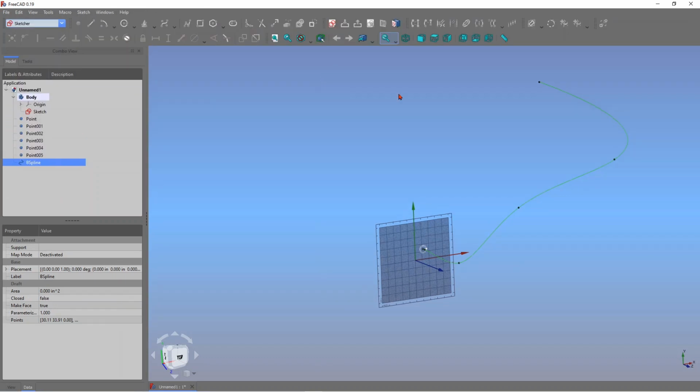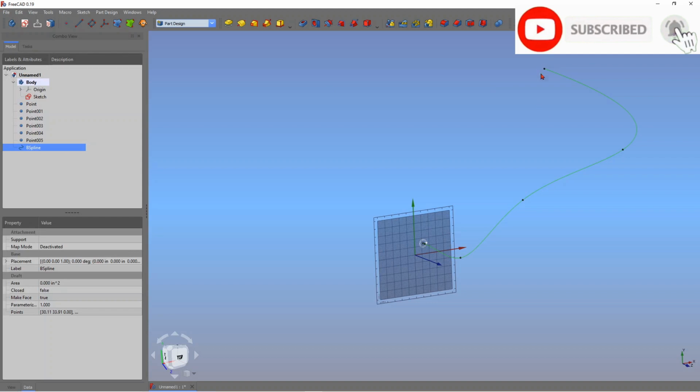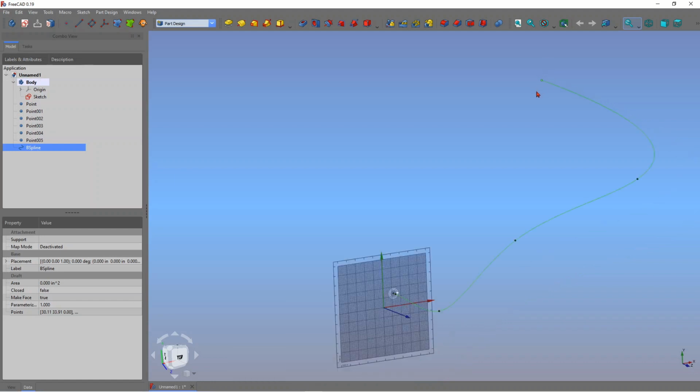Before we go into the sketch tool, we have to do a couple of things, because you can't just create a sketch plane. If you have to create a sketch here, you have to put a plane that is perpendicular to this line, or B-spline. You have to create that, right? If you just click on this sketch, the sketch will appear here. It's not going to appear here. So you have to do some work before we do that.